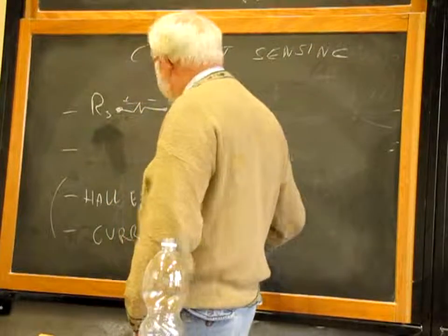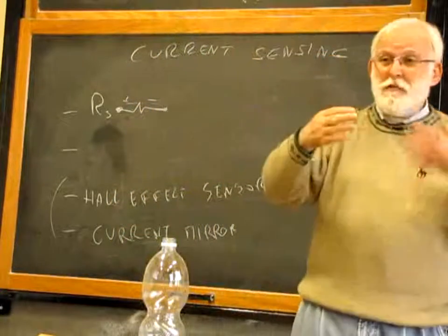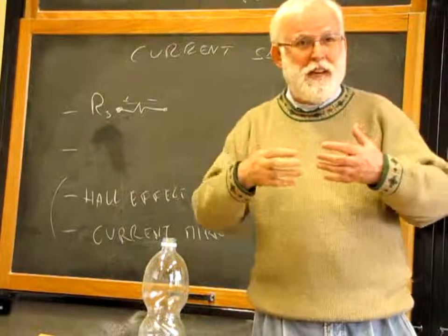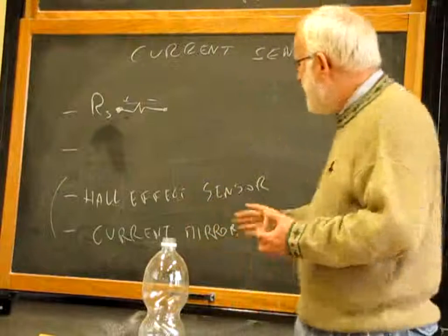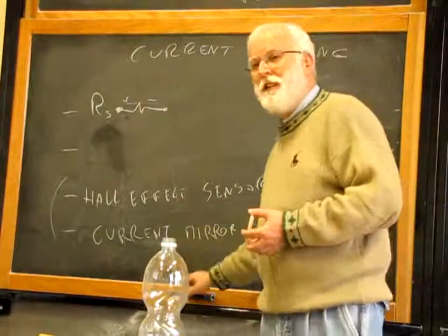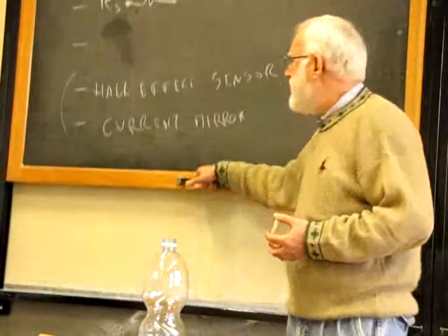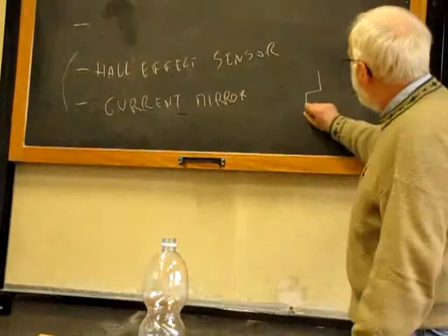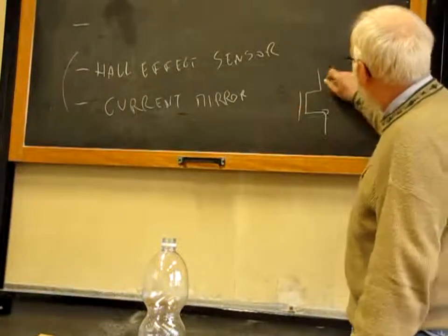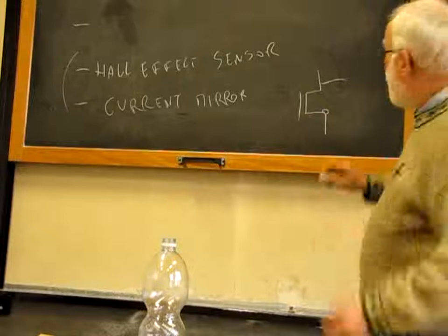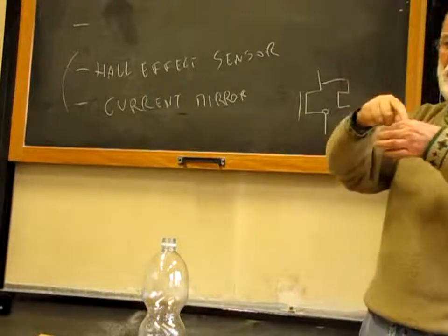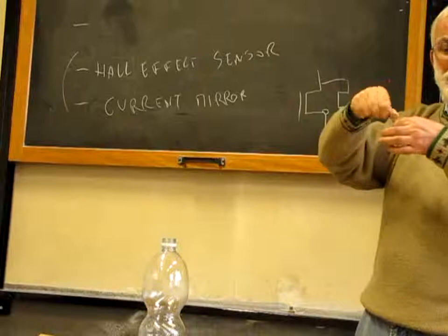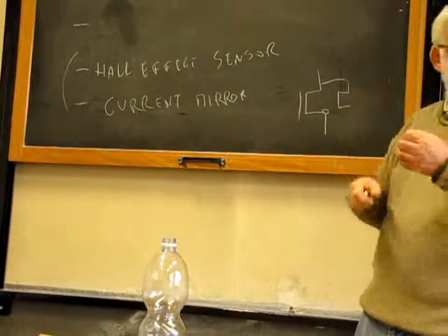Well, if you say current mirror and you think of the two transistors connected together, it's not really like this. But it was done. There was a device that was designed to work as a current mirror. This device was basically a large MOS transistor, and in the same piece of silicon there was a small MOS transistor in parallel, which means that just a small area was disconnected in one part.